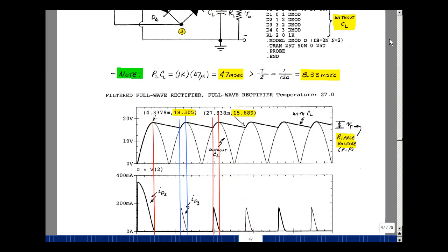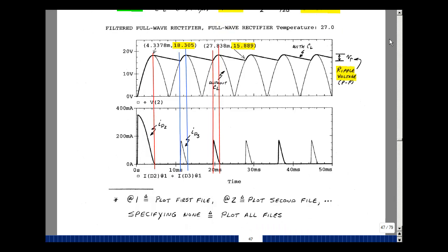And here's my output. I ran 2 simulations, and I wanted to show you what the effect was without the capacitor, and that's what our bridge rectifier is doing. And then when I ran the capacitor, you can see the effect of it. It followed the waveform here, and then as this went back down again, this began to just droop slowly, and eventually this catches up to it, and then it goes back up again and it repeats itself.